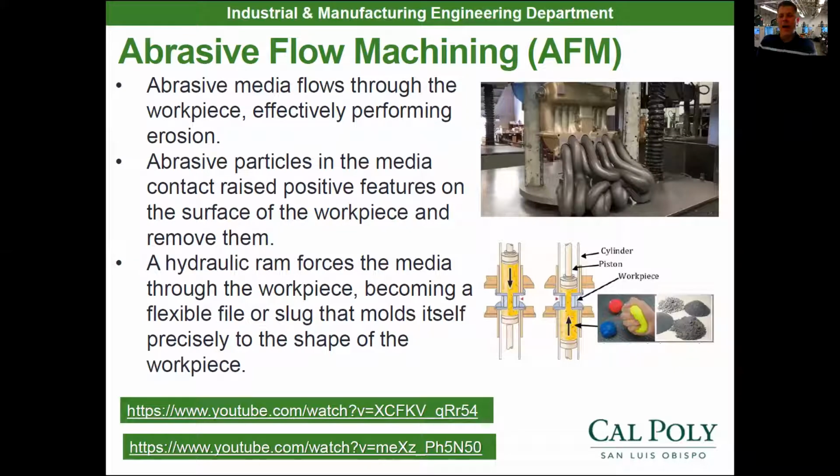So when you have a casting, you don't want any flash or anything like that if you have some sort of port that's going to carry a fluid. So you deburr internal casting ports with this abrasive flow machining process. Now I have videos from the aftermarket automotive industry. The bottom one here, I'm not going to watch during this time, but they're abrasive flow machining some Ferrari heads and Lamborghini heads, and they're getting more power out of them because they're able to smooth out where the air flows into the engine. But I've got diesel exhaust manifolds instead.